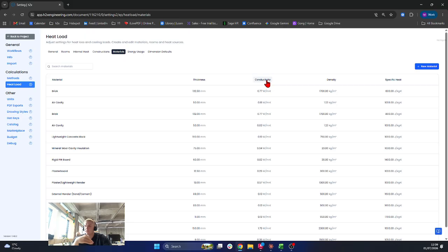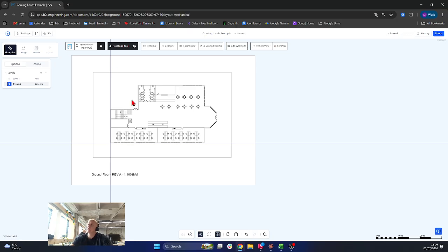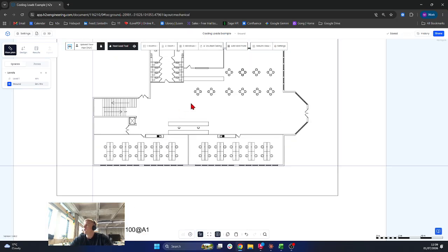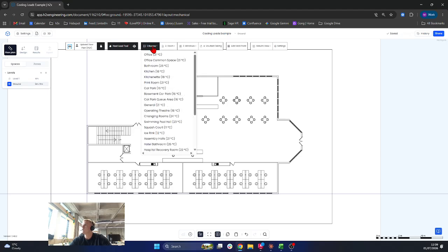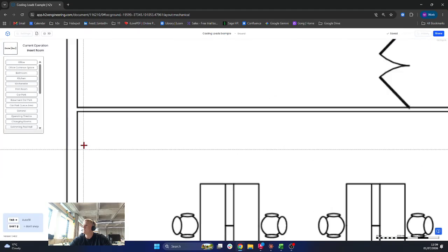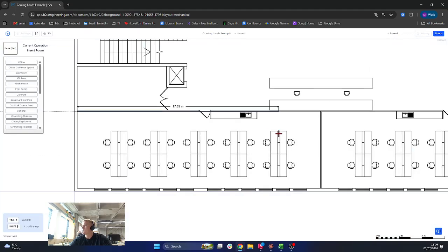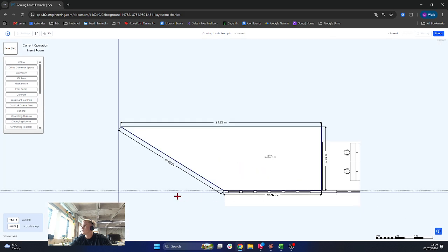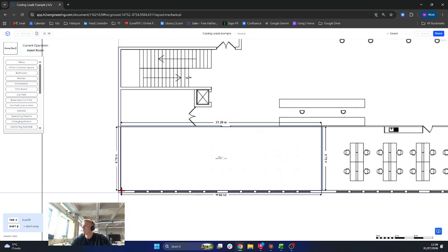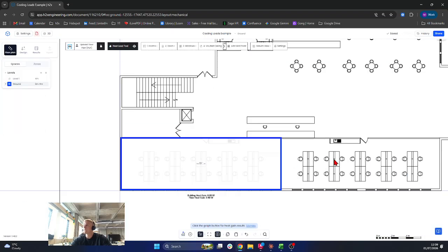And they can be saved and templated per job and selected at the beginning of any new design, like we did on this particular project. Okay, now let's go into this design process here. So if I select a room type, I can simply draw around those rooms marked on the plan. Left click in each individual corner, like so, and hit escape once we've done it.